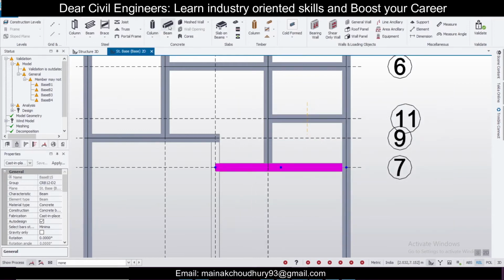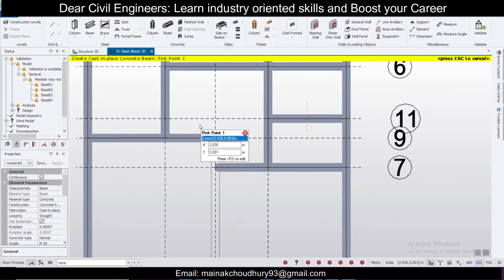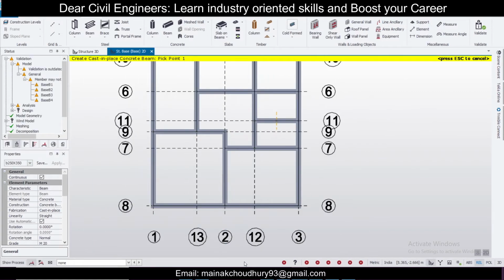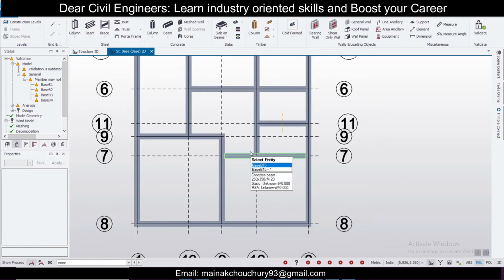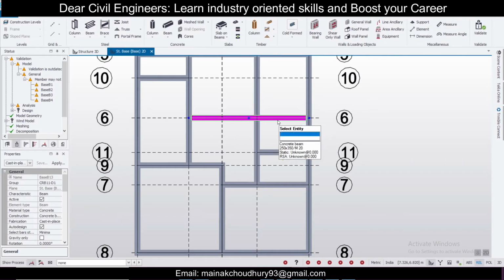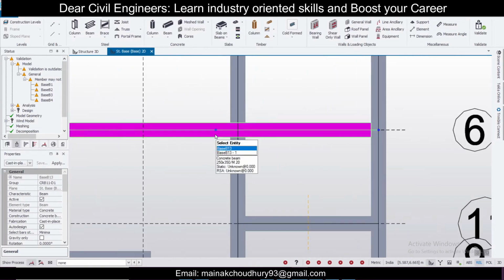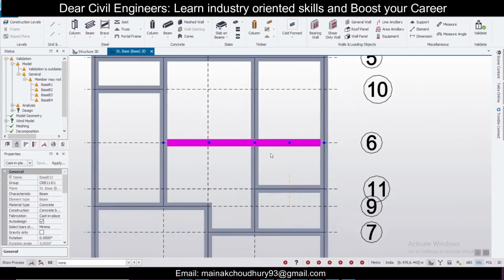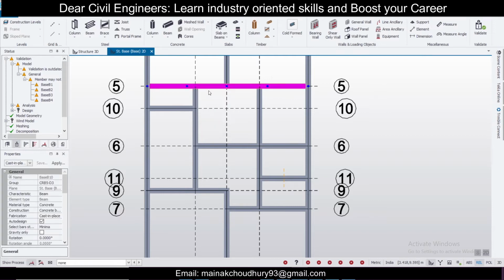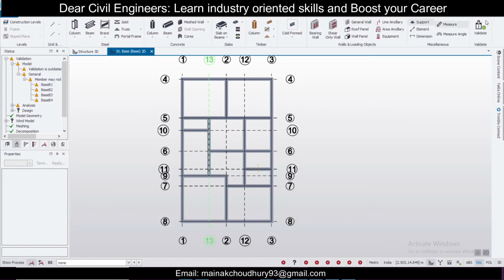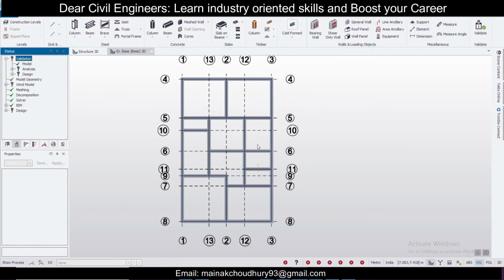Okay, go back to beams again and take the beam which you have selected, and after that join the beam. So we're done here, and now you're going to check for any overlaps. Like here there is an overlap, so select this point and make it up to here, and if there are any other overlaps we will see a warning. So let's check here in the validate option. So there is no overlap or no member collision or no duplicate members, we are all good.